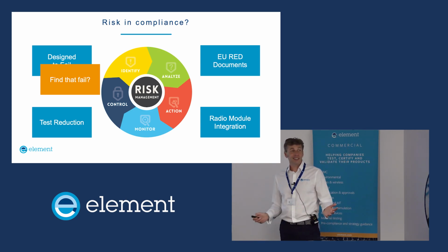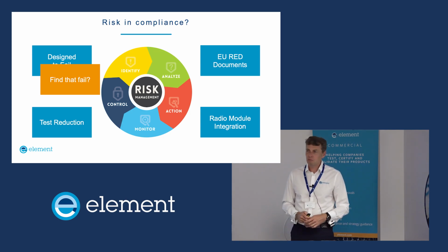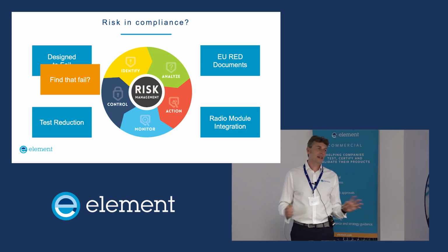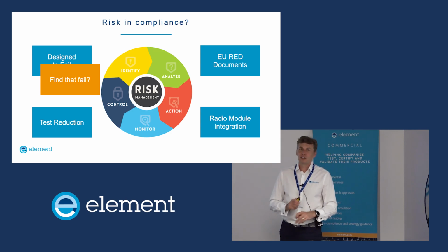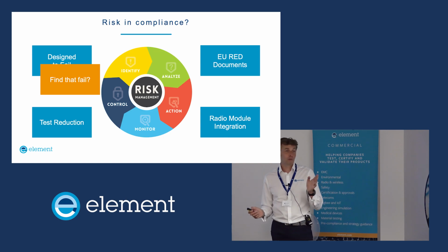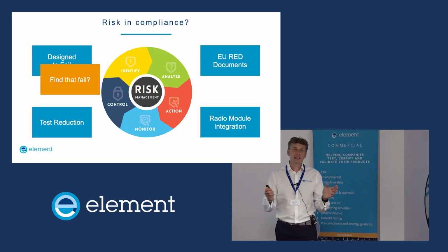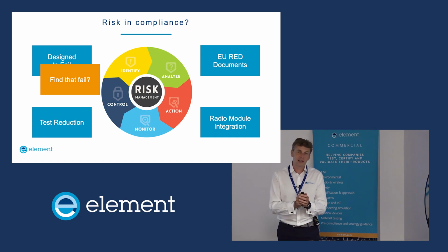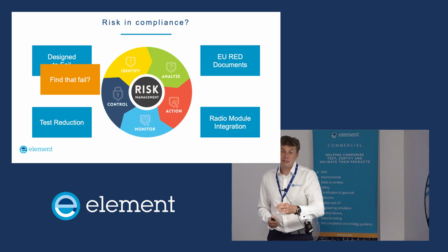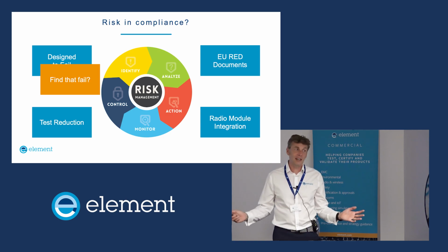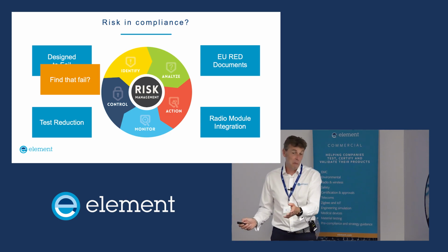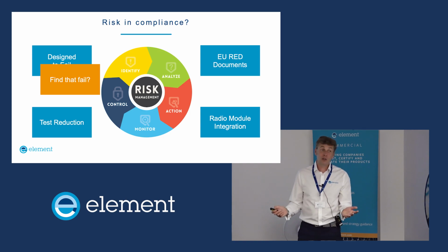Test reduction then, just listening to Alex, you might go, well, we don't do test reduction, we do full testing. Full testing, complete full testing, we don't do any test reduction. Great, okay. So let's say you've got a radio transmitter, you test bottom, middle and top channels. Well, Bluetooth has 79, 80 channels there, so that's 3 of those channels you've tested, and you're making an assumption that all of the others comply. This laptop was probably fully tested in 1 or 2 modes, but we've just said it could have hundreds or thousands. It might have been tested with a fully shielded HDMI cable, or maybe not, but people will have made a decision.